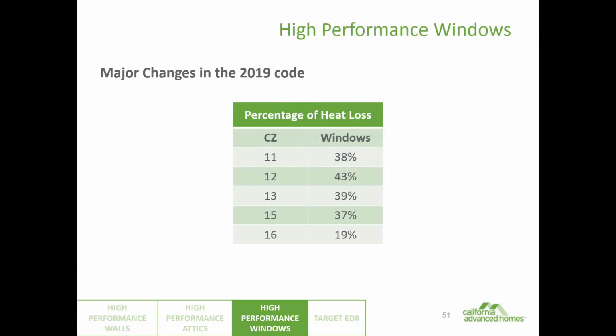And I've seen model runs with a U factor of 0.2, solar heat gain of 0.2, or a U factor of 0.15, a solar heat gain of 0.15. It's really challenging, right? That technology of window does exist now, and I hear that's kind of where Passive House is right now, but the general market is not there.